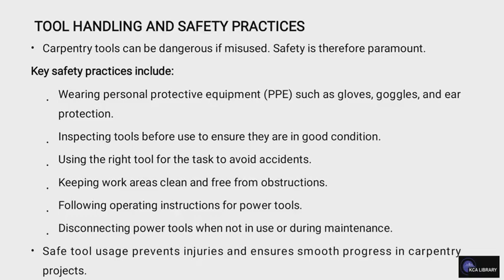Carpentry tools can be dangerous if misused, and safety is therefore paramount. Key safety practices include, one, wearing personal protective equipment such as gloves, goggles, and also ear protection. Inspecting tools before use helps to ensure they are in good condition.